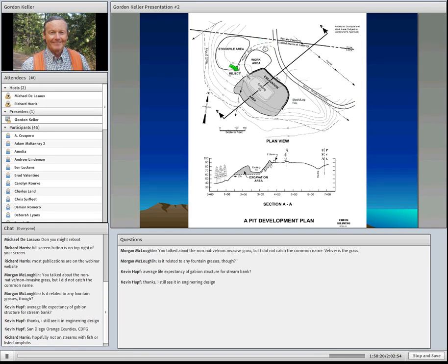Down here in this cross section, what do I want it to look like when I'm done? Do I want to leave a pond here? Do I want to leave it draining? Do I want to leave a steep back slope here, or do I want to leave it really flattened out for public safety? These are all issues that are operational, but they also affect the reclamation of a site, particularly conserving the topsoil that's got the organic material and the seeds from the local site to help promote revegetation, and what the slopes look like, which affect both safety and erosion in the site.